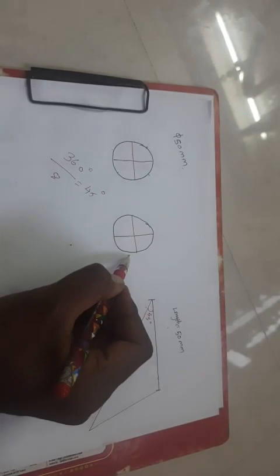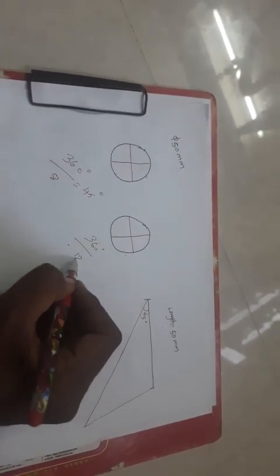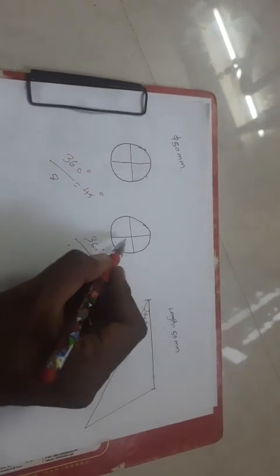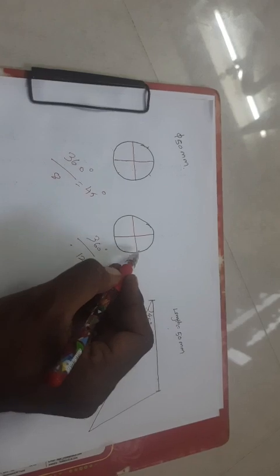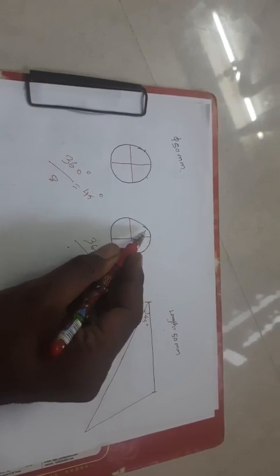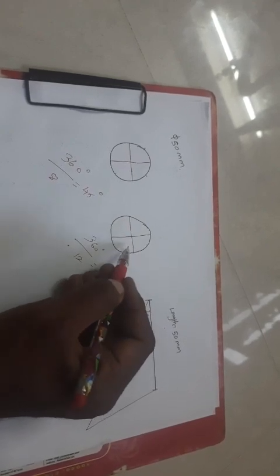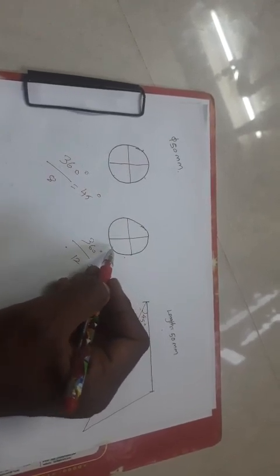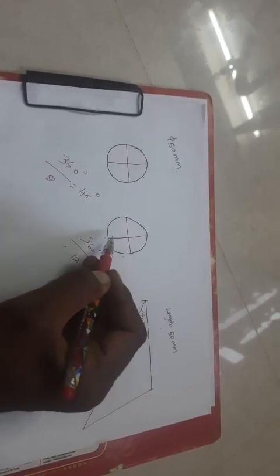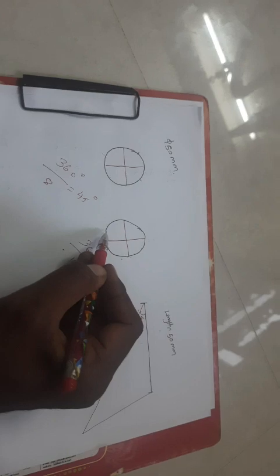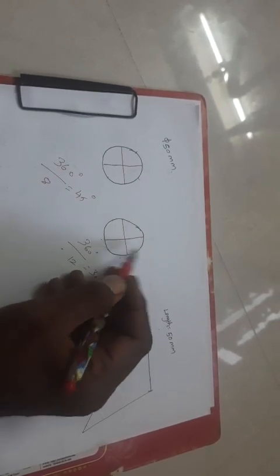If I am going to divide the circle into 12 equal parts, 360 degrees divided by 12, I am getting 30 degrees. So keep your protractor here and mark 30-degree points: from here 0, 30, 60, this is 90, and from here 0, 30, 60, and this is 90, and then up or down 0, 30, 60, 90, or from 90, 120, 150, 180. Mark the points and connect those points.